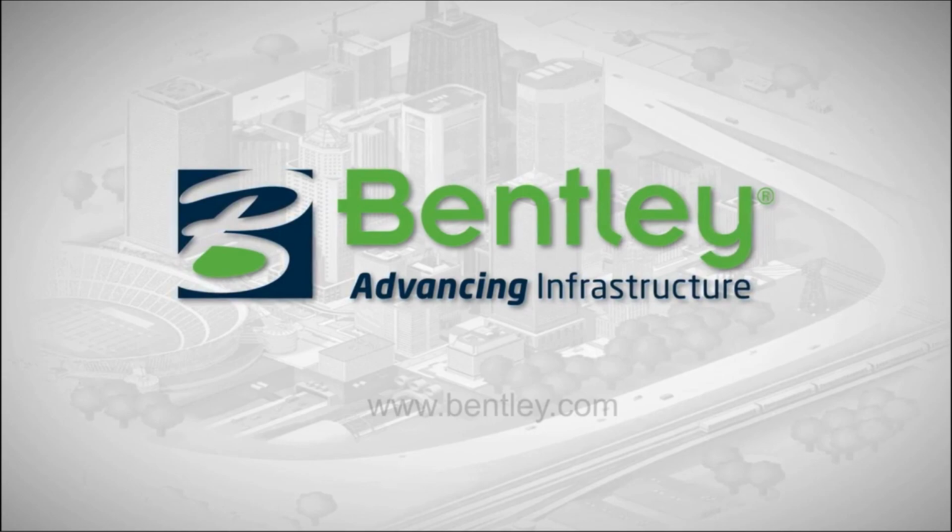Yeah, sure. RCDC has a concept known as a style manager, where the user can go in and specify the organization's preferred layer system, so layer description and color, dimension style, fonts, and so on. Also what sort of bubble you want for a grid mark, what sort of section mark you want, and so on. It's a library you can select from, and you can create a customized drawing style. This drawing style can be set as default, so whenever you generate an output, it will use the organization's default style.